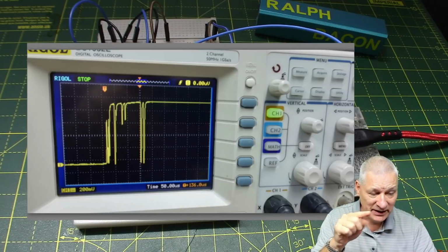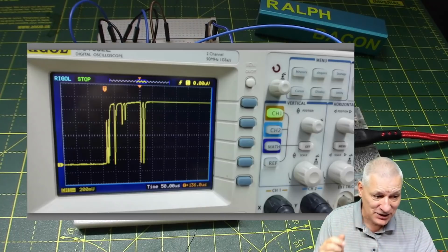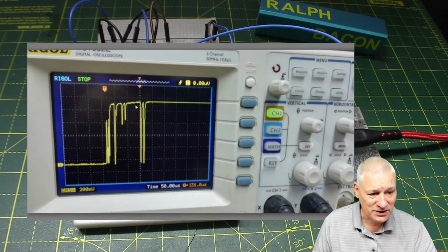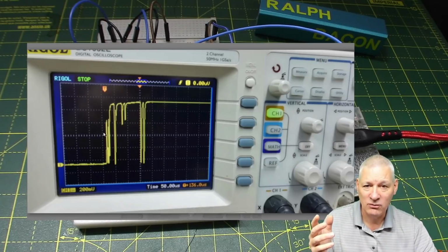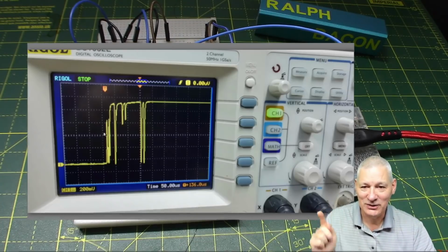So here's a picture. Now this is the worst switch bounce that I've ever recorded while I was doing all these experiments. It never was this bad normally, but as you can see here, the number of times this goes up and down, and then not even all the way down to ground, like it just bounces about and eventually settles. That is a good example of what, well, bad switch bounce is. Yeah, let me show you another one.